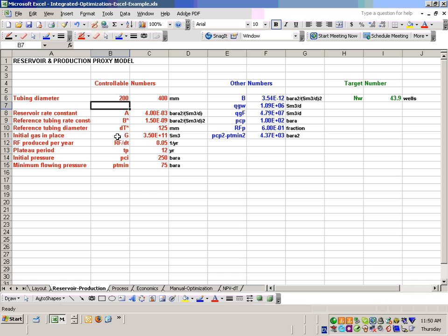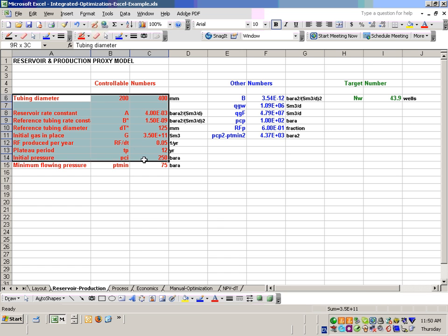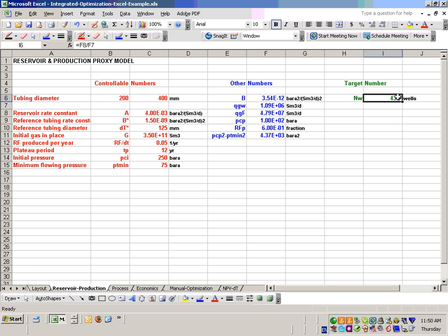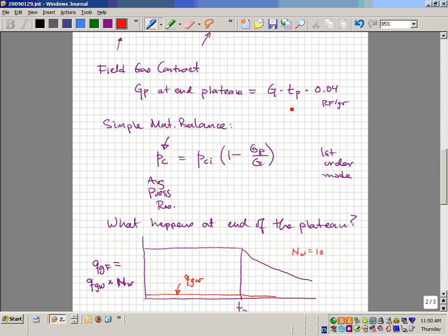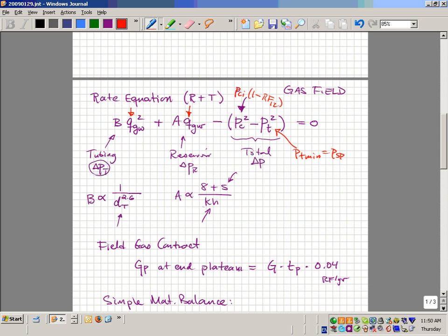But again, if you've got all these key variables and you've got a key result, that's this model. Any questions? And it combines what Mike was talking about. It combines in this equation here. This is a direct solution to the IPR plus vertical lift calculation. It's a single model.